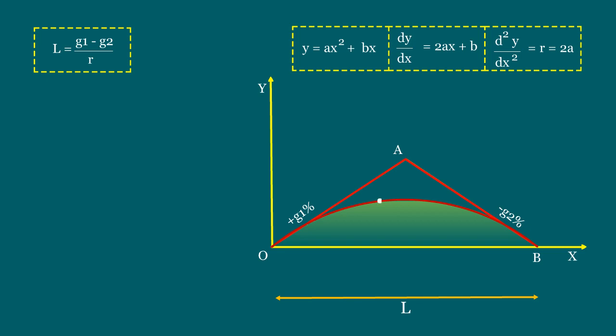Now, let us mark a point on the curve, having the coordinates of x and y. And name that point as Q. And let us draw a vertical line, PQR, through the point Q. Here, the length of PQ is the vertical distance between the tangent and the point Q on the curve. And it is known as the tangent correction of vertical curve. And it is denoted as h.